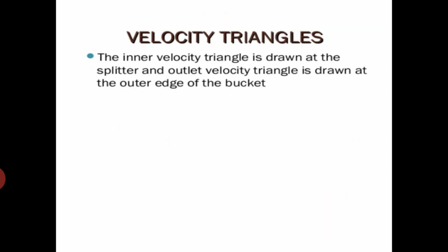In the velocity triangle, how to draw a velocity triangle for this particular Pelton wheel bucket? It is very important to draw a velocity triangle. The velocity triangle helps us to calculate the force exerted by the jet, and also the work done by the jet, or the power of the jet can be easily calculated through the velocity triangle. And this velocity triangle can be drawn at the splitter and at the outlet of the bucket.